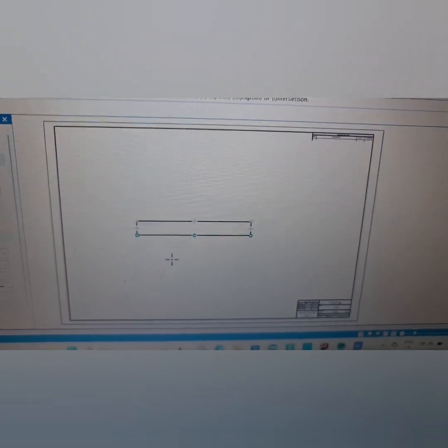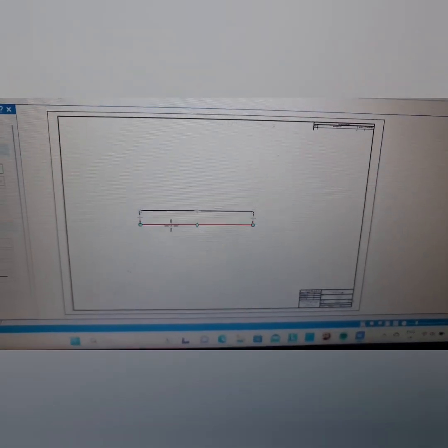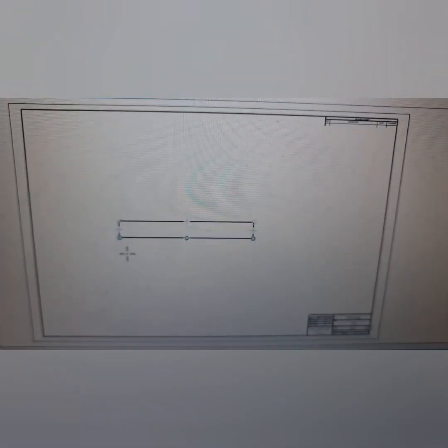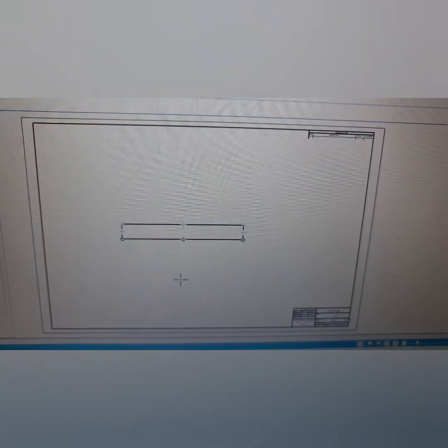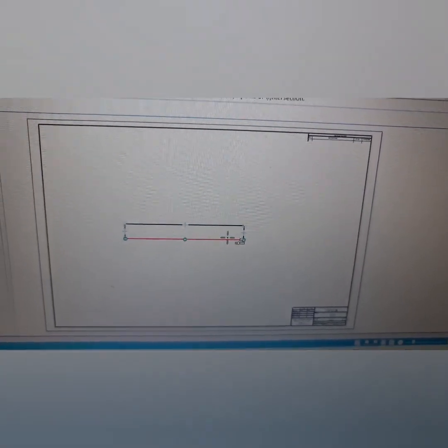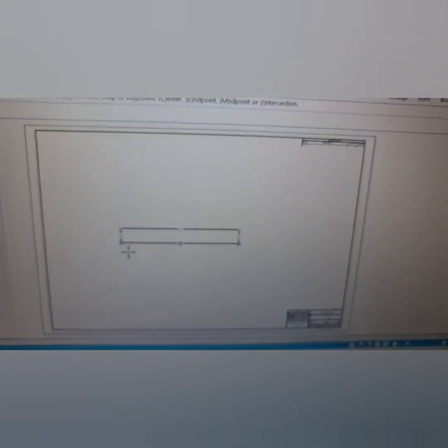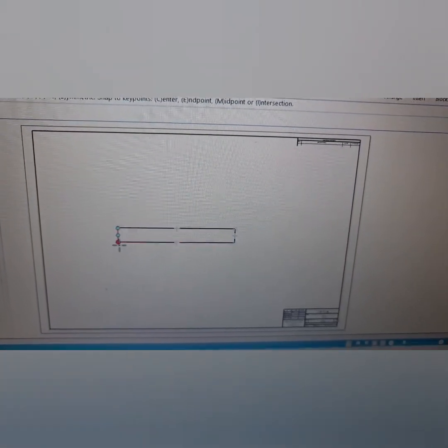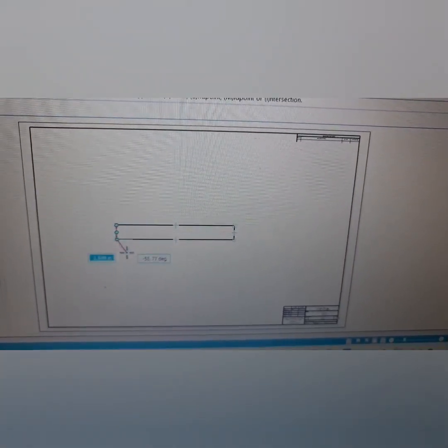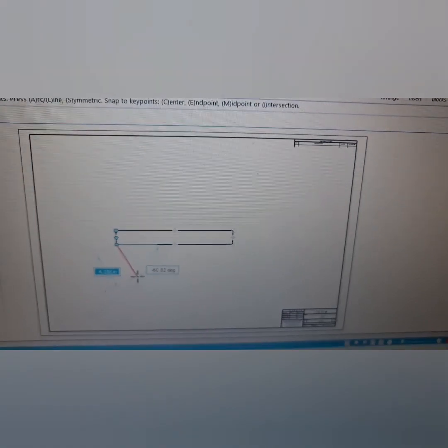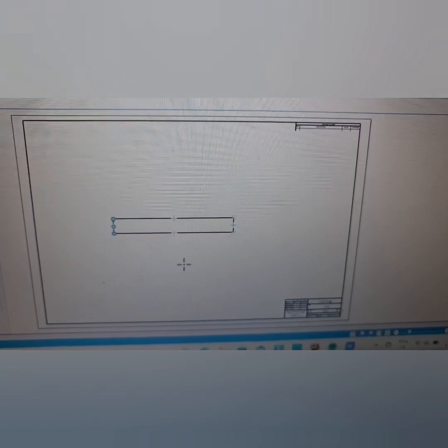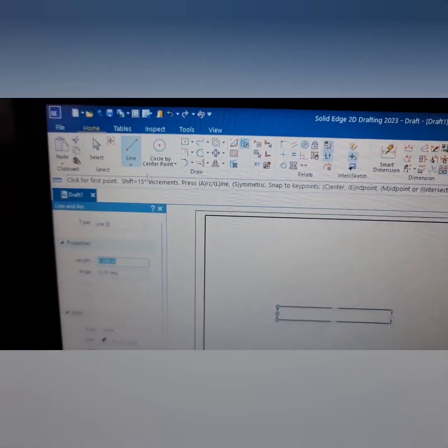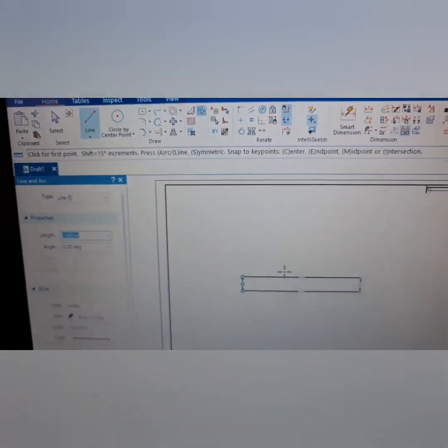So if you go to put your next line in, one thing I'm going to show you quickly: because I've plonked that one, it's automatically taken away the drawing of the next line, it's not automatically adding it. If you want to stop it doing that, or you go to snap on the wrong place to start your next line, so if I went there for instance and I was like, oh no, I don't want to start there, click your right button on your mouse, does away with it, but it's still selected the line point, yeah.